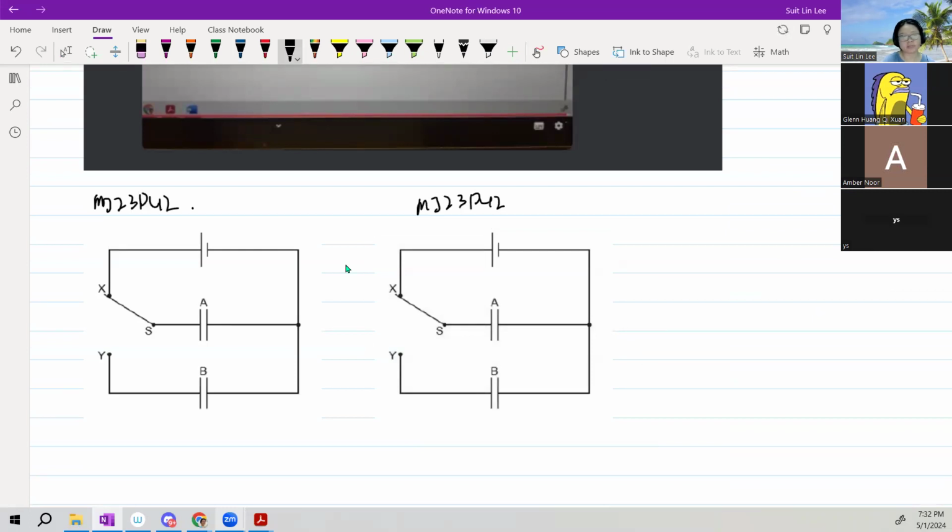Okay. Maybe you tell me what you mean by CTVT in this question. Currently this one is V. This one will be charged to V. This is not connected, this is 0 volt. Is there energy stored? In this capacitor, this is C and this is 3C. There is energy stored only in C. So the energy here is half CV squared.